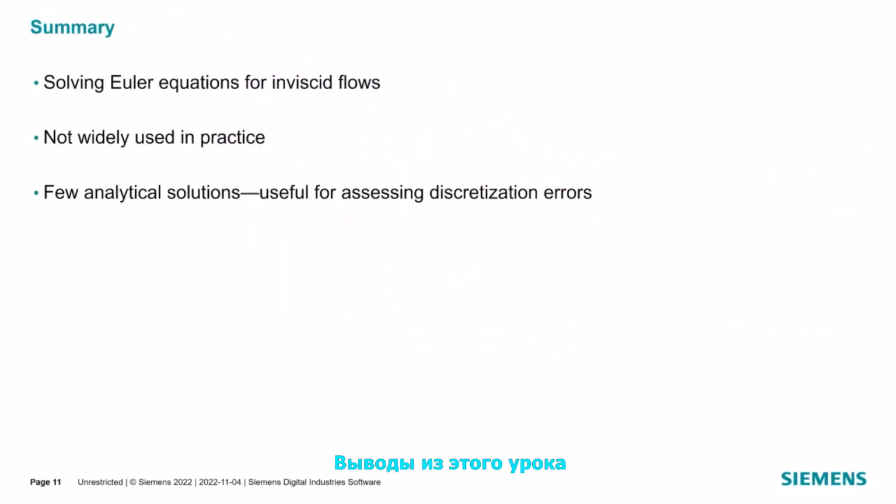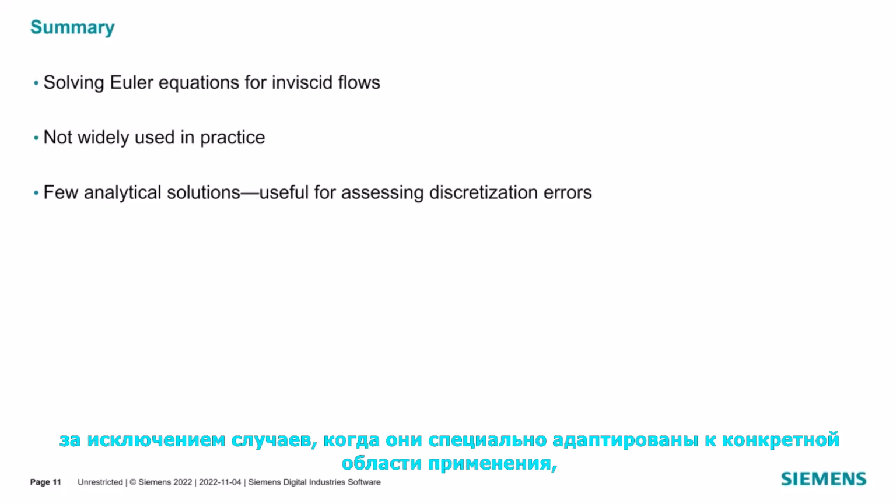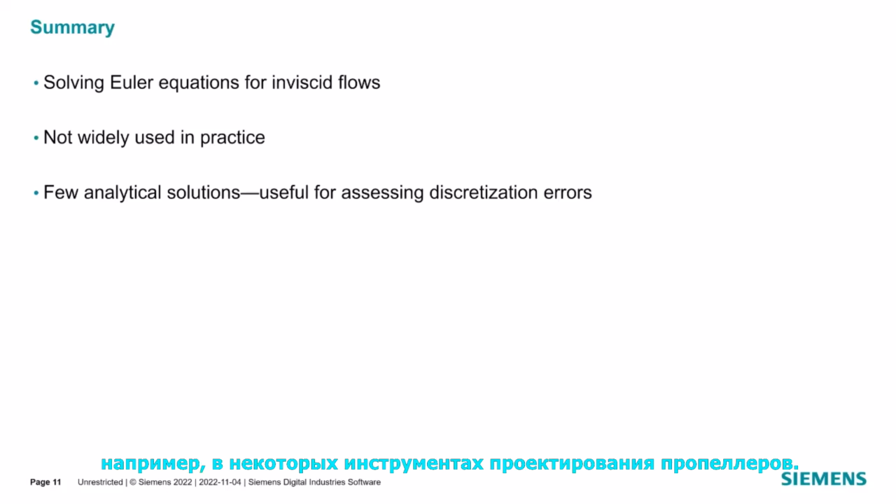The conclusions from this lesson can be summarized as follows. Inviscid flows can be computed using Simcenter STAR-CCM+ by setting fluid viscosity to 0 or by using the inviscid flow model. Euler equations are then solved instead of the Navier-Stokes equations. Inviscid flows are not fully realistic, and simulations of such flows are seldom used in practice, except when specially tuned to a particular application, like for example in some design tools for propellers.